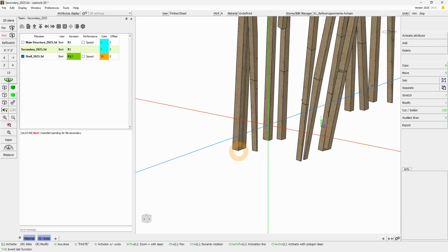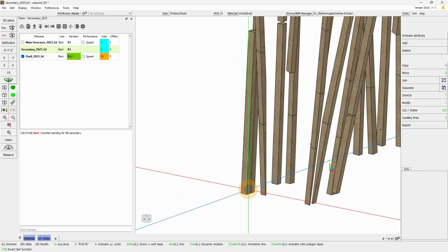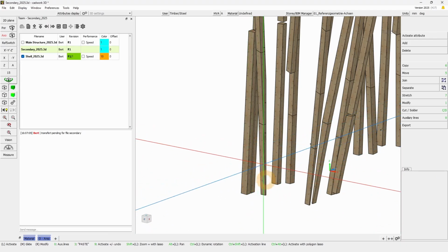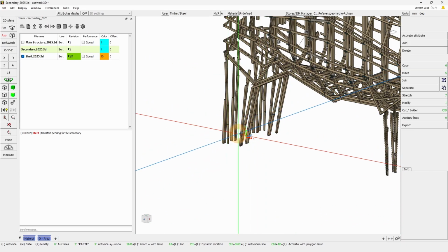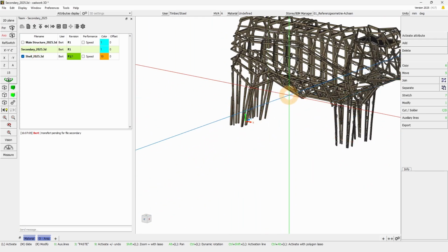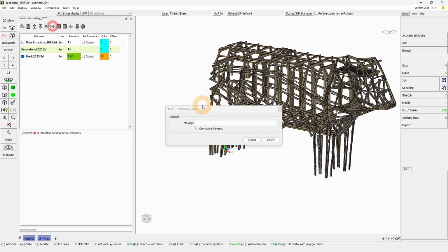Now we have this second element. Let's say that we do a modification. To modify this, actually I'm just going to leave it this way for now, not going far in depth in actual modeling. So here it means that this file is actually modified. It's a new version. In order to update or upload that new version, you will need to commit your changes. And here you would use the arrow pointing right to commit. The other one is to revert, so to load a previous revision. So here we are going to commit this new revision.